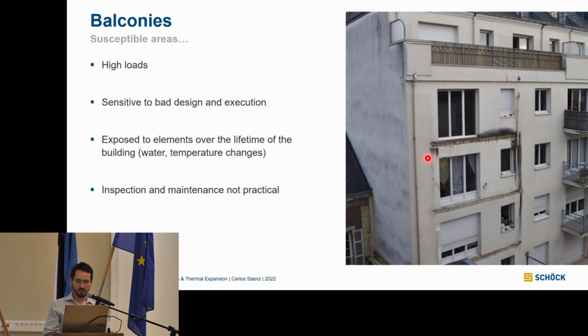Here was supposed to be a balcony, and you see some mold formation here. What happened is, well, you have this element exposed the whole life, for the next 50 years, to wind, to sun, to snow. So it's a good example. This is not a thermal break connection. Let's say it's just a standard balcony connection, but it helps to make my point clear.